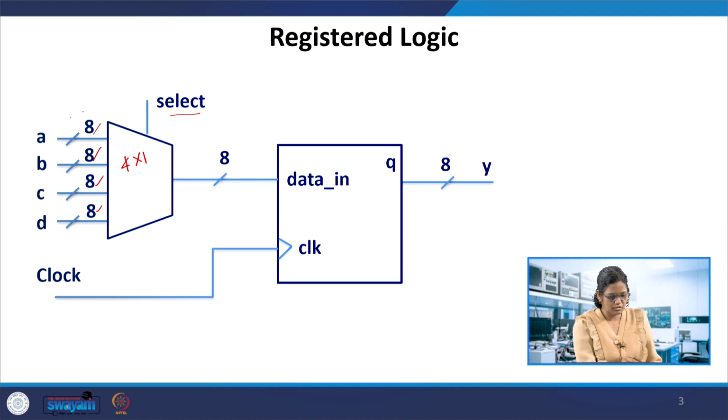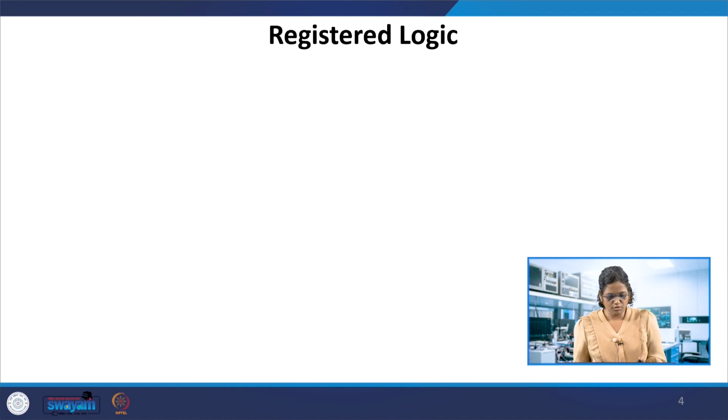This is good enough as combinational logic in the multiplexer. But if we want this mux to be registered, that is, the output is registered, then it should be passed through a flip-flop, and at every clock edge the data input is given to Y. The 8 bits selected from A, B, C, D will be passed on to Q. So this is combinational logic, but to have the output variable registered using the flip-flop, how do we do that in the Verilog code?